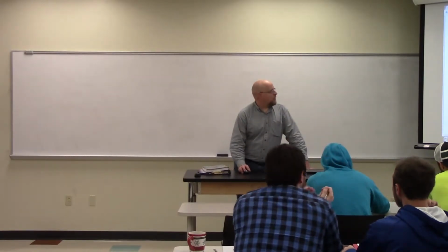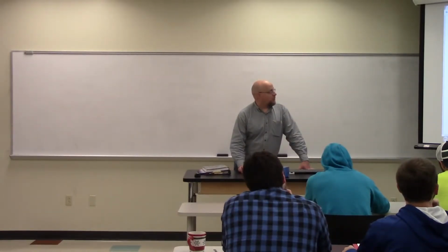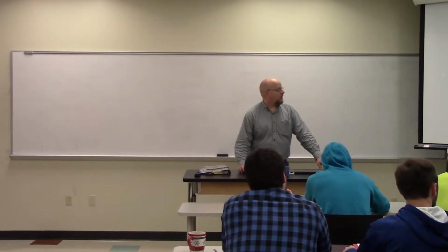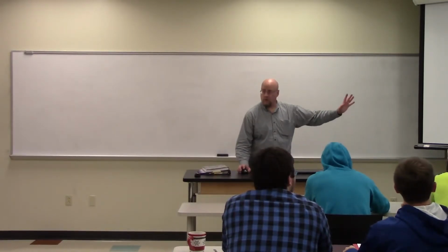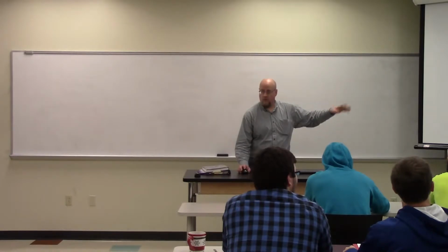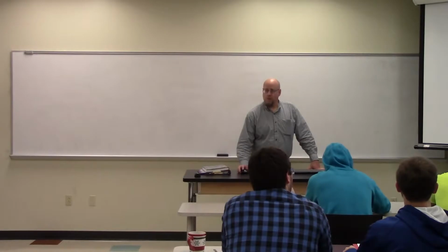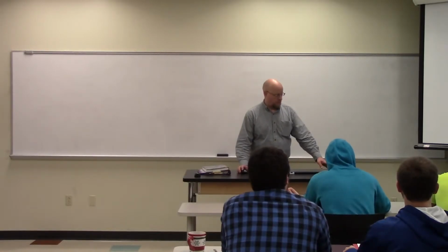But only a few. Okay, so the phase diagrams. You got to be able to distinguish what kinds of phases are present in each region. So what that means is I gotta know this is alpha, without the labels, because this one's labeled. You gotta be able to identify, this would be alpha lead, this would be liquid, this would be alpha plus beta, this would be beta, beta plus liquid, and alpha plus liquid. You need to be able to identify what two phases are present.